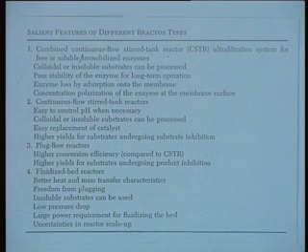Then in the case of plug flow reactors, it has often been noted that the conversion efficiencies are much higher compared to CSTR, and there are two major reasons for that. Broadly speaking, we will see the quantitative analysis of reactor performance in both cases, but the major reason is that most enzyme reactions are inhibited, if not very excessively, then mildly, by product concentration.